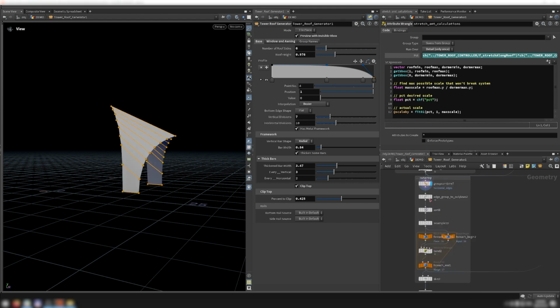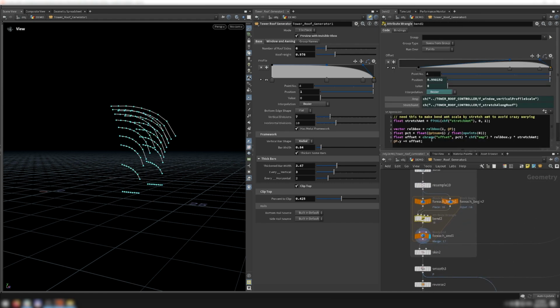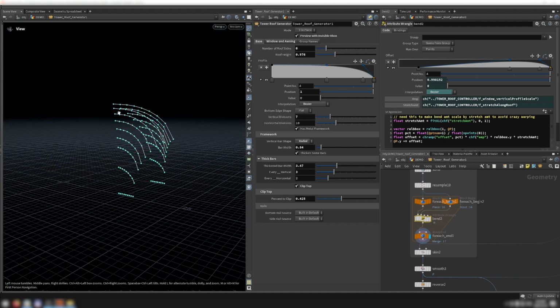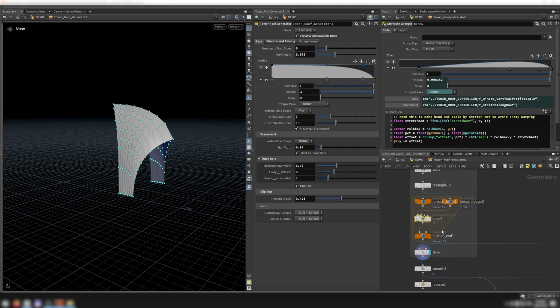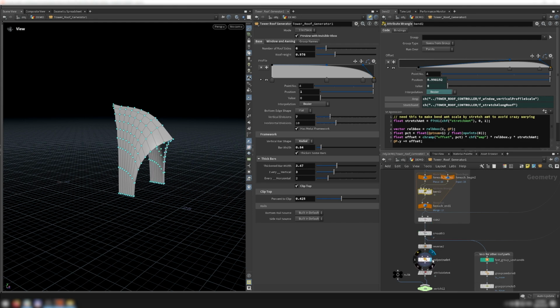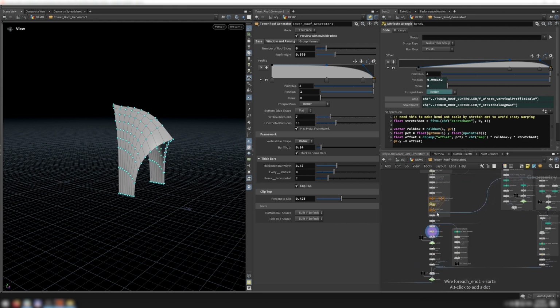Lastly, I curve the top of the awning by turning it into lines, resampling those lines, bending each of them based on the tool settings with a vertical falloff so that the top lines get bent more and the bottom ones stay straight, and then I reskin the geometry. Then I just smooth it out and extrude it, and the surface of the window awning is done.